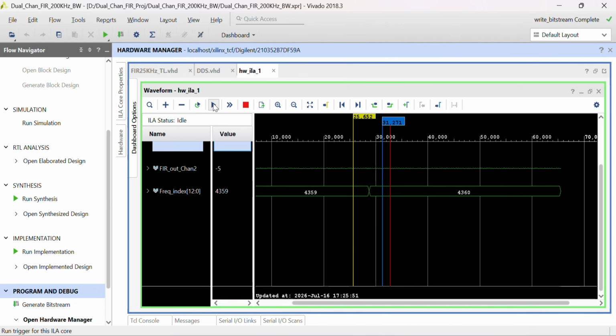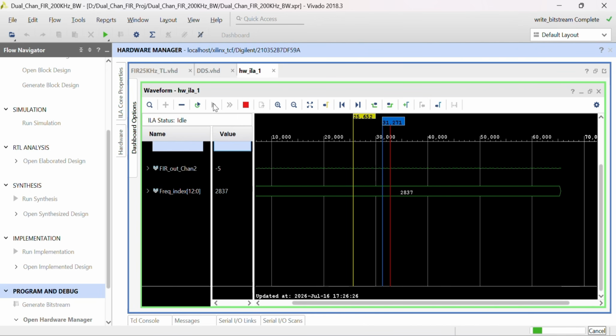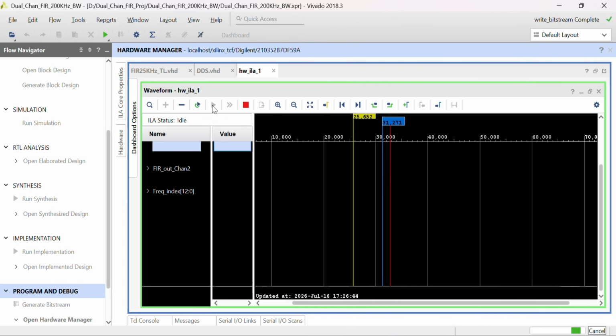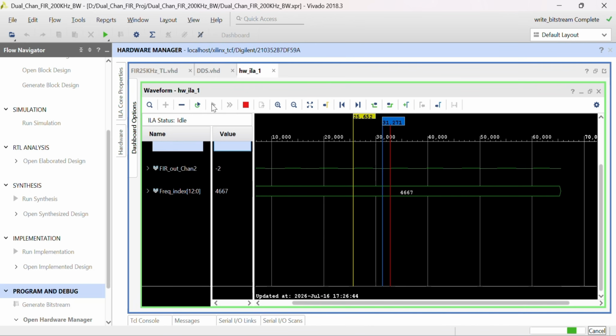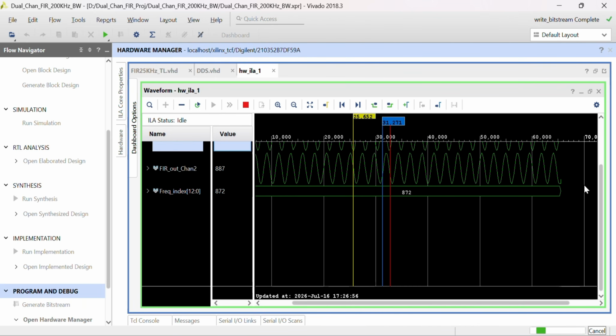So we repeat again. Same thing, nothing coming out, and this is because the frequency we are looking at right now is 283 kilohertz, so it's not coming out. So another one. Our passband is supposed to be between 0 and 100 kilohertz. Seems like we are not lucky yet with capturing low frequencies. One more. We have to be fast. Okay, here you go, we got something here.